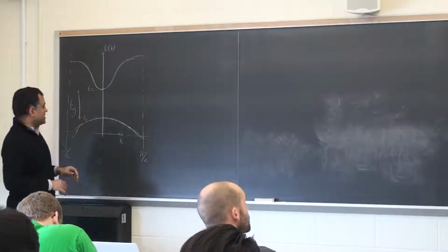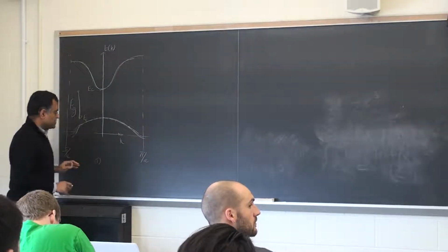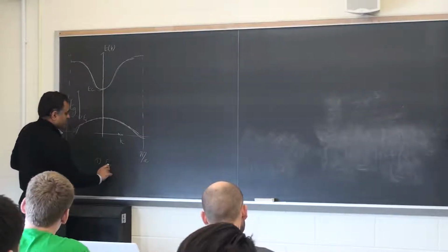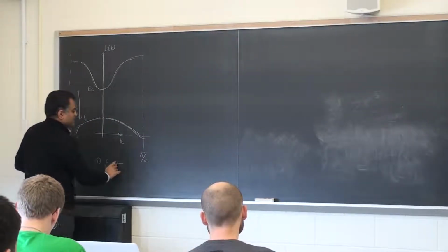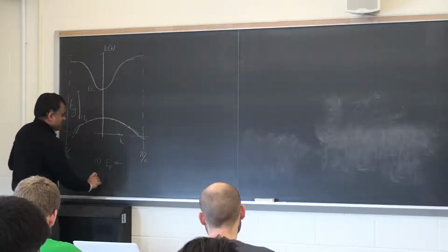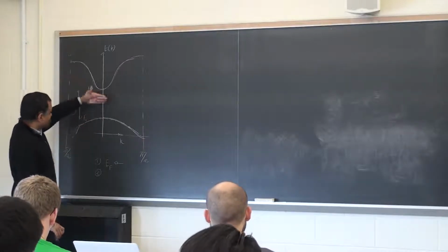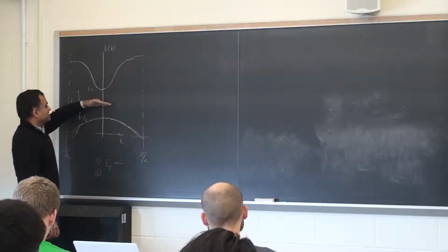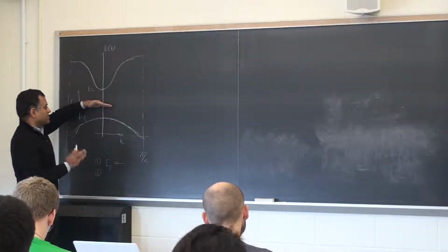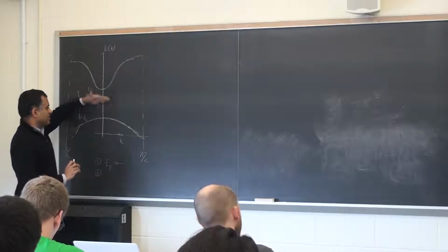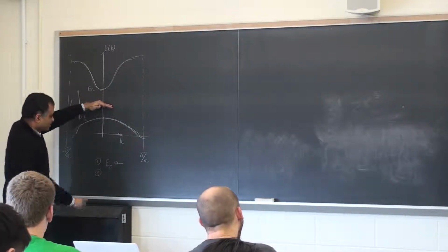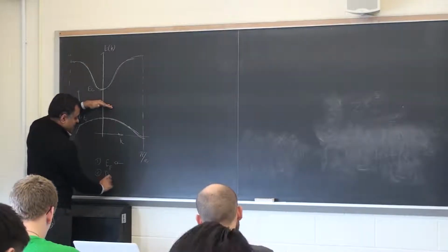So the first thing we'll talk about today is where is the Fermi level of this semiconductor, and we'll find a very precise answer. Second is the Fermi level, wherever it is here, probably it will be somewhere in the middle of the gap. And as far as flowing current through it goes, it's going to be extremely difficult if the Fermi level is in the middle of the gap because it has very few carriers to give you, right? So how do you put carriers in the semiconductor?